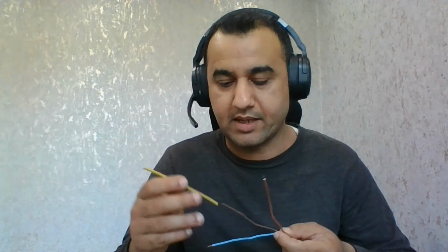But the process is the same. So you need to put a sleeve on top there, and that's going to be the circuit protective conductor. This is going to be connected to your Class 1 equipment, 3-pin plug. So the bodies of your appliances, such as toaster, kettle, microwave, cooker, whatever you use, are going to be connected to this circuit protective conductor.